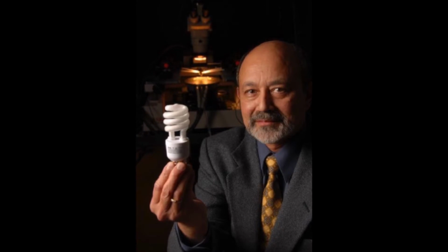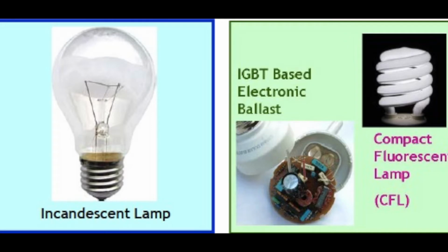Lots of papers covering a whole swath of topics, from advanced displays to power semis, bio-MEMS, analog circuits, all that kind of stuff. Two things struck me, and it's a very big show, so I'm only grabbing two. One was in the power semi space: the founder of the IGBTs, the bipolar transistors used as high voltage power switches, explained and showed numbers on how the efficiencies brought by those devices have greatly decreased gas consumption and electrical costs in motors and things like that.